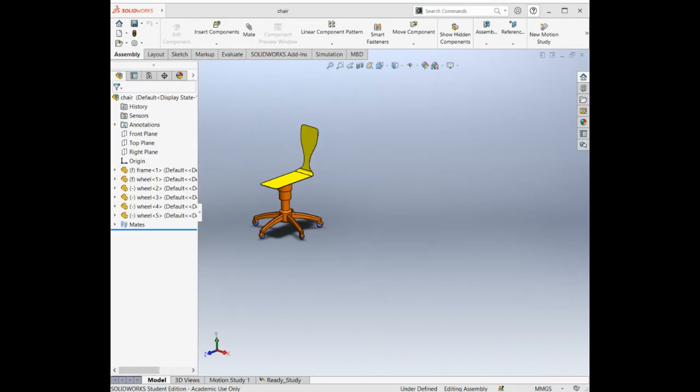Here's another static analysis you can do. They're loading that boss, on that opening section, and you can say what material it is and load it up there. In the end, you always end up with your mesh, and then you end up with something like this. I can see that von Mises thing, the criterion we use, and it tells you where your yield strength is. This 8.9 is your yield, and obviously we reach it. So on those round circles, probably the lift tests, and the corners, there's some stress concentration, and that's where it's most likely to rupture, there or there.